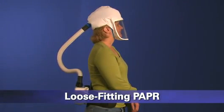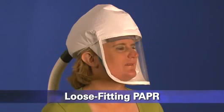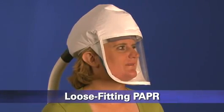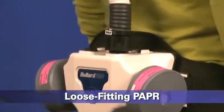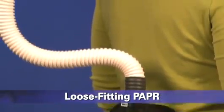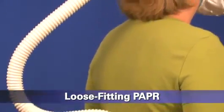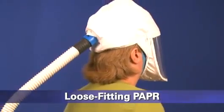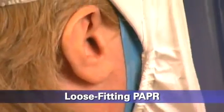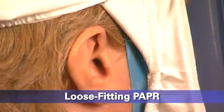This is a loose-fitting face-piece hooded powered air-purifying respirator, also known as a PAPR. A PAPR has a blower that pulls air through attached filters. The blower then pushes the filtered air into the face piece, which covers all of the wearer's face. Since it is loose-fitting, it does not need to be fit-tested and can be used by workers with facial hair.